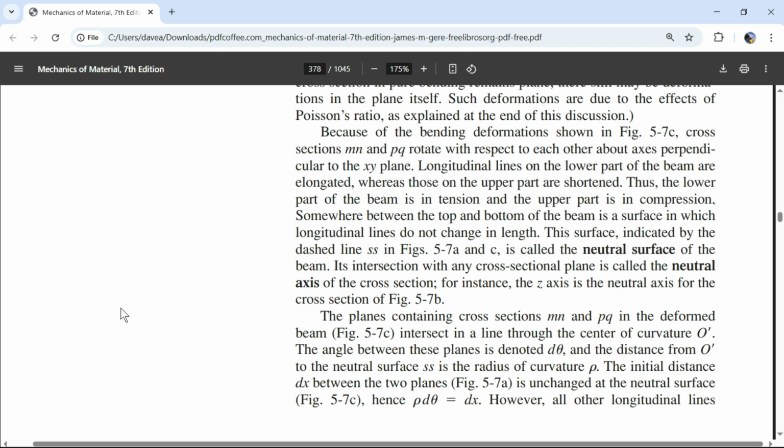But we have plenty of strength up to that point, so we just make sure we don't exceed it. And we don't need to know that we applied 100 pounds. I can take another specimen with the same dimensions, pull on it with an unknown load, and then measure how much change in length. If I measure the change in length, that is synonymous with the load being applied.